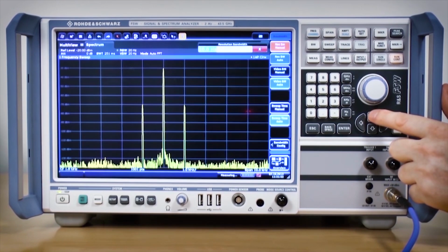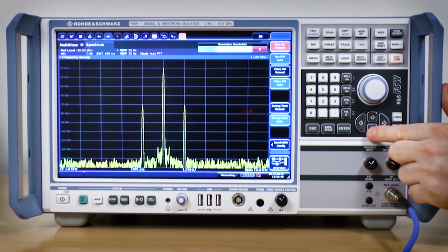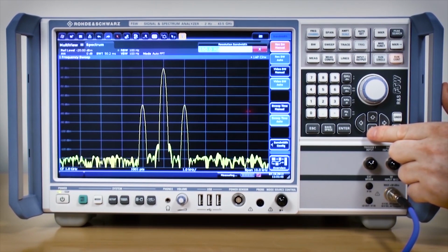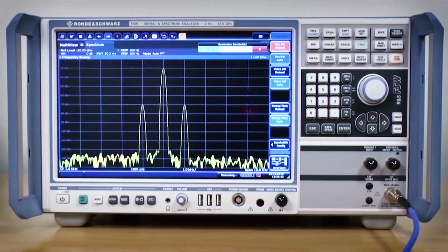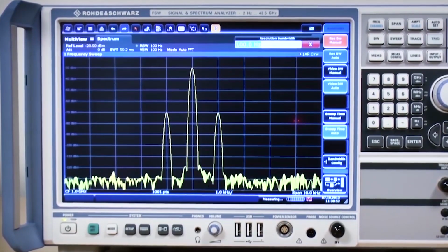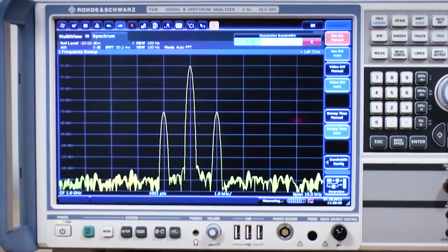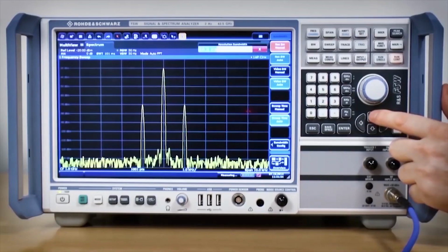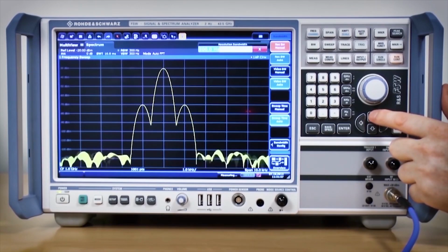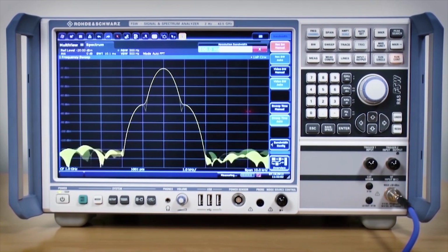The downside to a narrow resolution bandwidth is that the scan takes longer to perform. As a result, the spectrum analyzer links narrower resolution bandwidths to smaller overall scan widths. Otherwise, they just take too long. The noise level also falls for lower resolution bandwidths because the noise is proportional to the bandwidth. This means it's easier to see lower level signals because they are not masked out by the noise. Taking the resolution bandwidth on its own, it is possible to see that the detail is lost. For modern spectrum analyzers, the resolution bandwidth is normally automatically chosen to provide the optimum resolution for any given case.